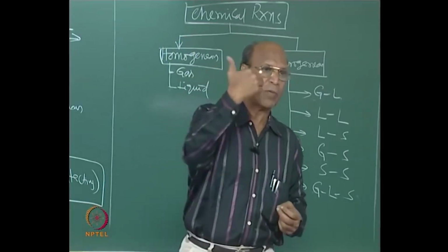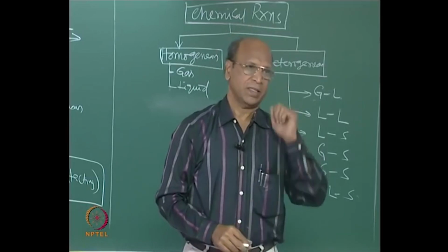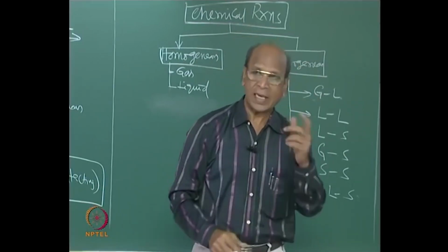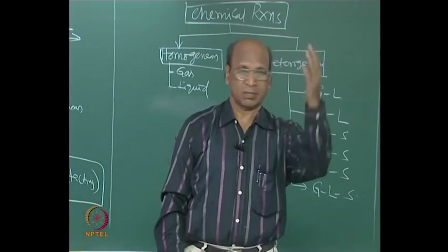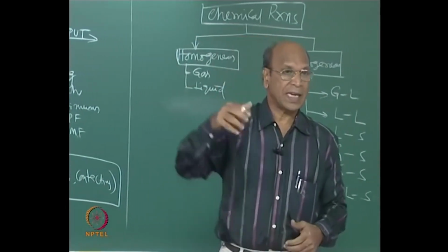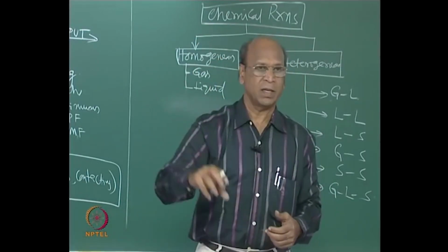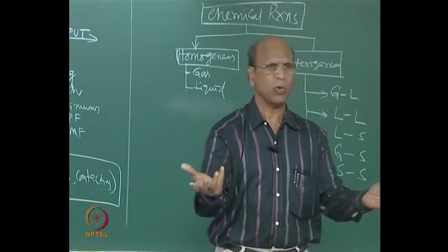That is why you will have effectiveness factors more than 1 in the non-isothermal case, but only for exothermic reactions. In fact, in the next semester you will get even an effectiveness factor of 500. That means the rate of reaction inside the particle is 500 times larger than the rate based on bulk, which is very good for us.